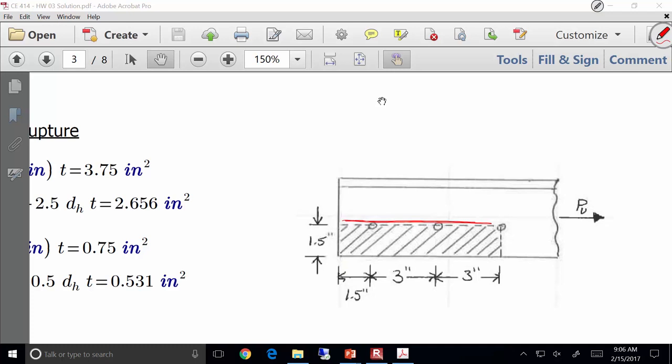And the gross area in shear is that line times the thickness. The gross area in tension would be this line times the thickness. And then subtract the holes accordingly. And again, I used a thickness of 1/2, so that was just for one block, then multiply by 2 at the end. Don't forget phi of 0.75.